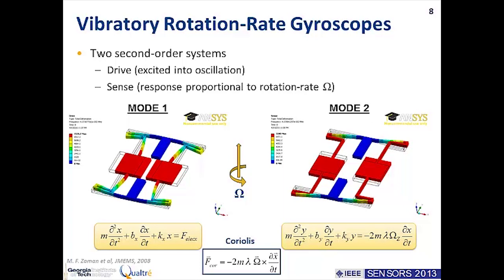The way you take care of that, and I think that will be covered in more detail during the interface circuit session, but in general terms, is by guaranteeing through control electronics that the amplitude of vibration of your drive mode is always constant. So you have an amplitude gain control system that compares that to a reference and keeps it stable.